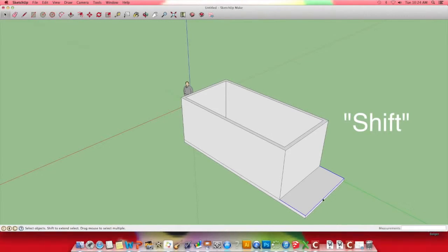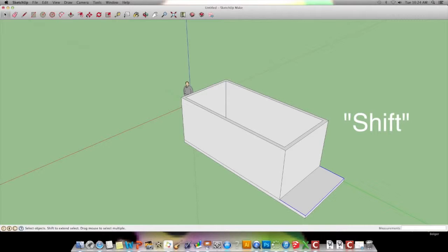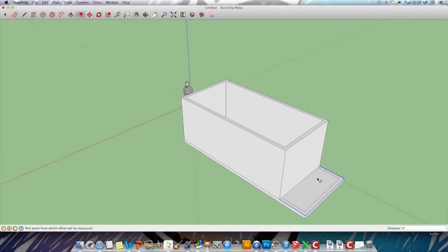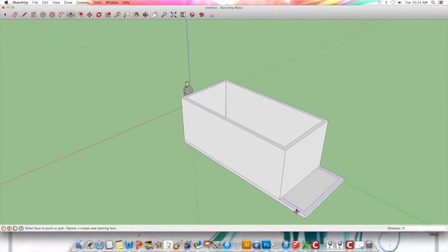So I just re-click the floor, and now holding shift the whole time, I selected the 3 walls that I want to select. Now I'm releasing the shift button, and I'm going to go to my offset tool, and this time I clicked once and released, now 6 inches, enter. It made the 3 walls, and now it doesn't have that extra wall. Again, I want to maintain my slab on the bottom to be separate, so I'm going to hold down the Alt button and rise this up.